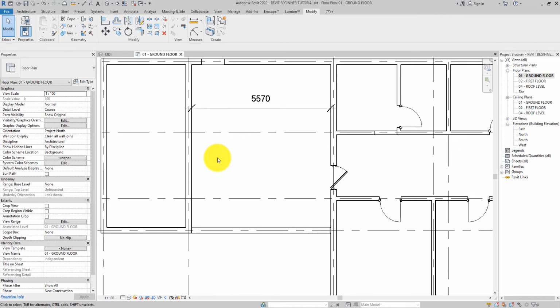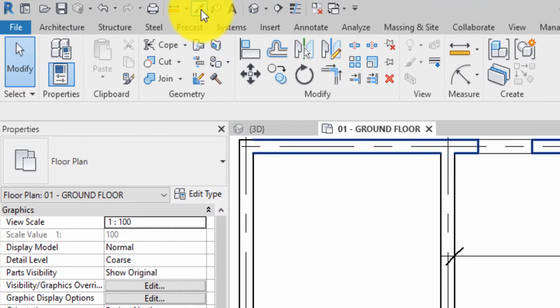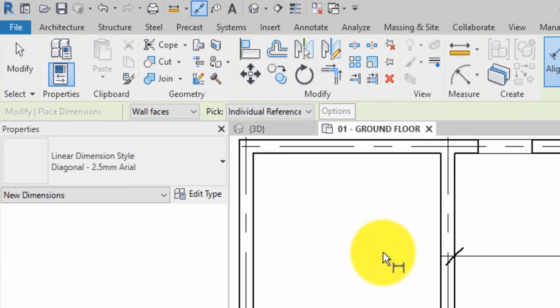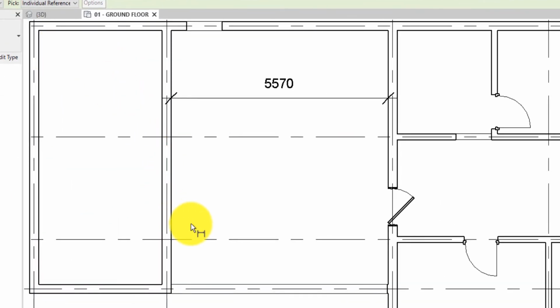Okay, must we centralize the wall opening? Nope, but since I'm the one calling the shots here, just do that. Centralize it. All right, to do that, let's grab the dimension tool again from the quick access toolbar. Our previous settings are still intact, so let's proceed. Let's select the two walls first and then the center of the wall opening.